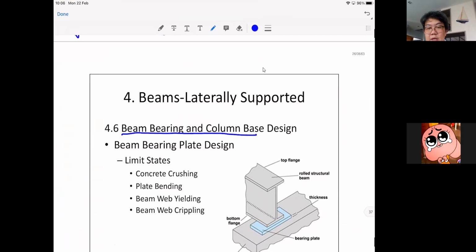Generally, you can have a situation where you must place the beam to sit on some other support. If this is some kind of concrete support, you cannot put it on the concrete right away. You need another sort of go-between structure so that you have the means to adjust the level of the beam.